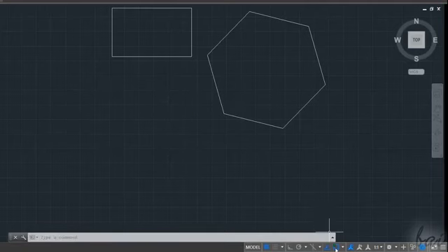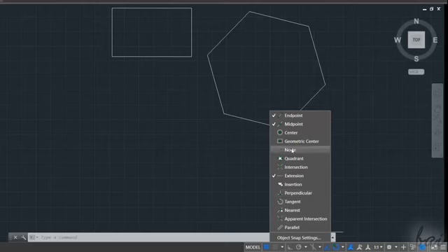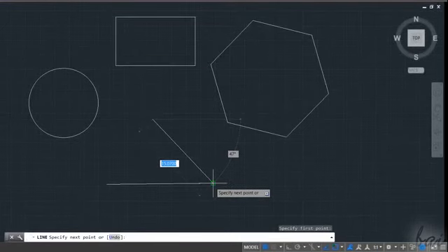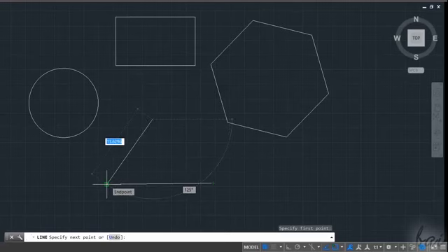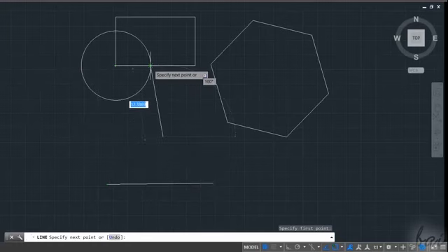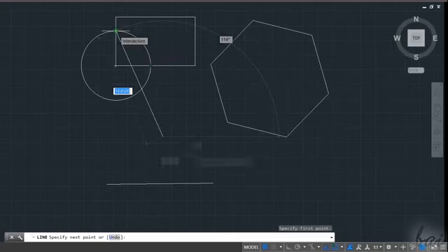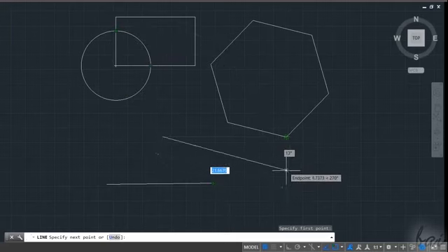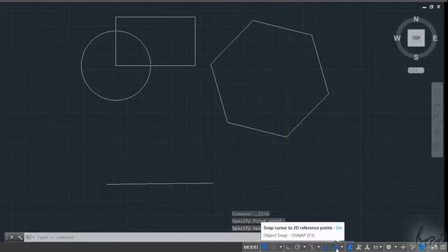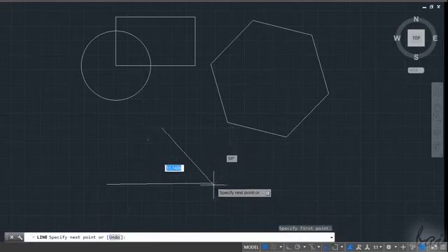You can also snap to drawings by enabling Object Snap. You can snap to several objects' points depending on the ones chosen from the list next to Object Snap. These points are well represented through green markers: endpoints through squares, centers through circles, midpoints through triangles, and intersections between objects through crosses. You can also use the green guidelines created by the green points shown. To disable object snappings, just click on Object Snap to disable it.